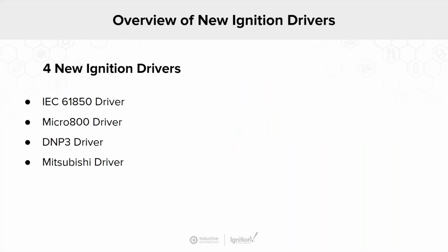So there are 4 new drivers that we'll be discussing today. The first one is the IEC-61850 driver, which is ideal for power monitoring and lets you connect to virtually any IEC-enabled device. Next is the Micro800 driver, which you can use to connect to Micro800 devices, of course, without having to use Modbus. The Micro800 driver lets you browse tags and access all data types from the controller, which is really convenient. There's also the DNP3 driver.